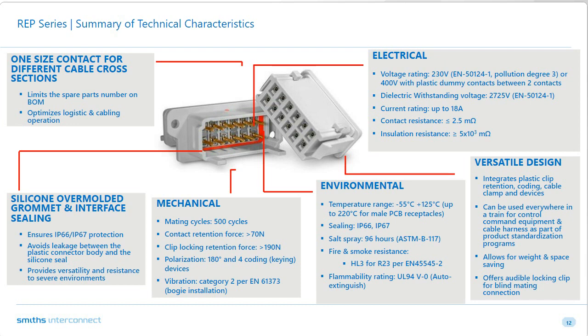And again, I connect back to the whole story. What happens when you have humidity, when you don't have a nice sealing around the connector? The humidity not only deteriorates the material properties, but that in turn, what does it do? It increases the contact resistance. And when you have increased contact resistance, I'm now sounding like a broken record in some ways, right? When you have an increased contact resistance, you've got higher power losses and it heats up, and so on and so forth. The failure mechanisms truly set off from that point onwards. So hence it is so very important to make sure that you have got a nice sealing around the front and the back of the connector.